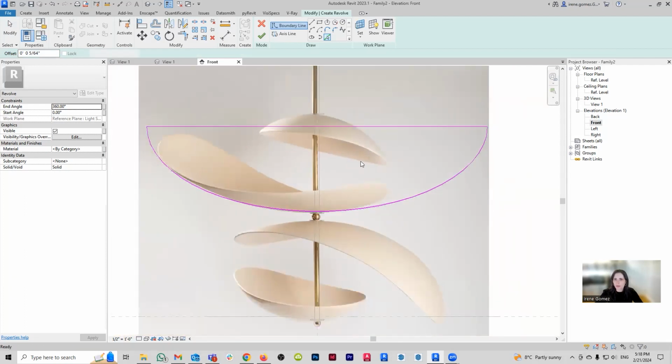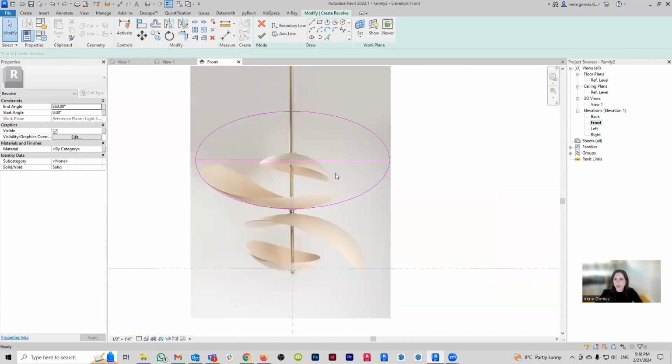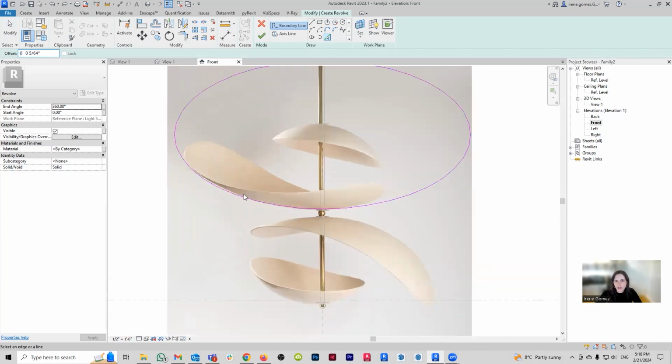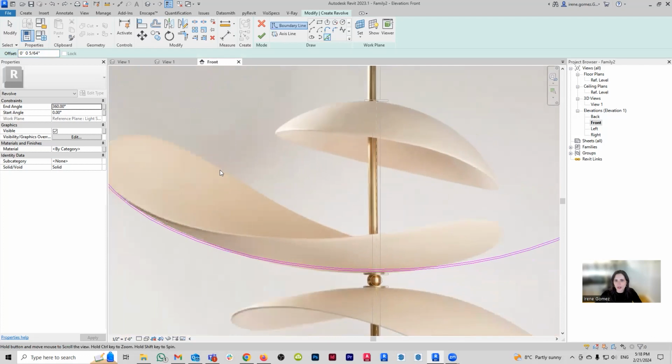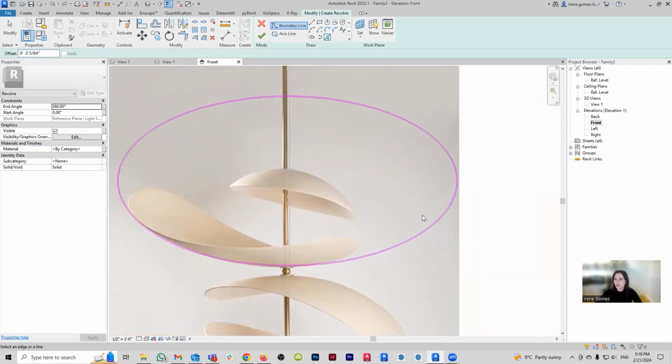Before I cut my watermelon, I'm going to offset it. So I'm going to avoid this and then avoid that. And I'm just going to go here to pick line and offset. And I'm going to say 2 millimeters. And that should solve the problem. Oh, there you go. See, that's much better. So again, the reason that it was getting distorted was because I had already cut it in half. And sometimes that can cause the offset to get a little bit confused.